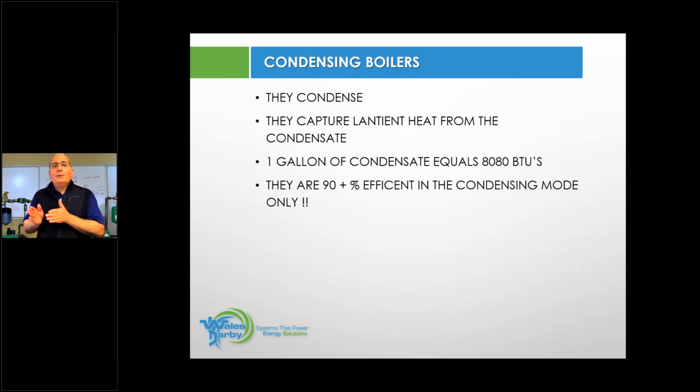All right, and the only way you would have known to do that is where we started today, by doing that heat loss. Once you've done the heat loss, you know the BTUs that you really need, even on a boiler change out. Now you have options, and you have more options for that homeowner. So if you're giving them a good, better, best, most of the time they may fall in the middle at better, and that could be that you're still doing cast iron, but you're still giving them outdoor reset, delta T circulators, all that kind of happy stuff, and you make more money.